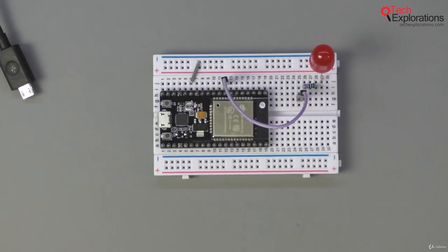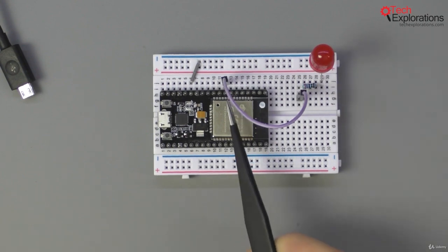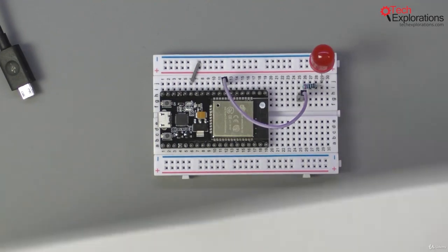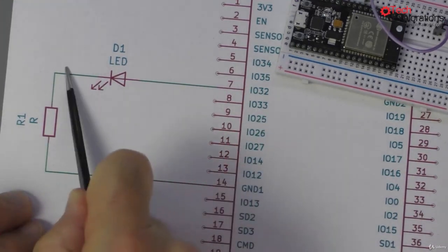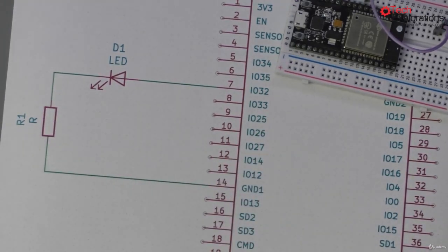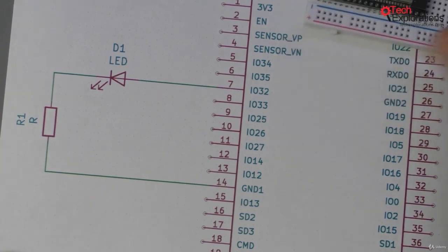So first of all, let's have a quick look at the hardware, which is very simple. As you can see, it's the same hardware and configuration that we used in the previous lecture with the blinking LED, and then move straight to the software and see what those additional capabilities in software look like. So I've got the LED connected to pin GPIO 13. Let's check out the schematic. Sorry, 33 I should say, so 32. Let's double check that. So I've got it connected to 33, which is okay.